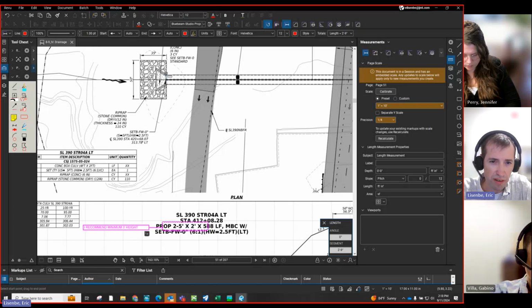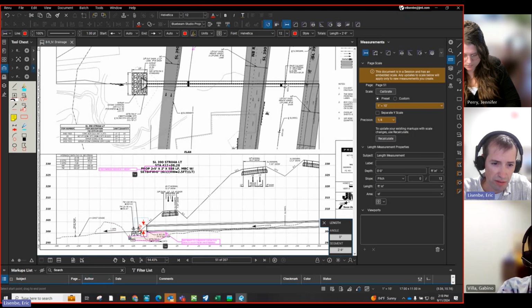somewhere around the head wall and come out a little bit, probably similar to what we have for the riprap pattern, and then go down to the right of way where we show grading through the sump. I'd try to work that out where I think we're going to tie into existing. So I'd probably set my grading area somewhere around like that.